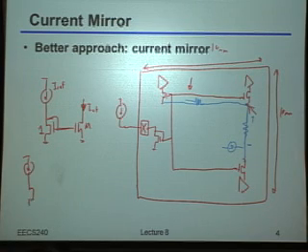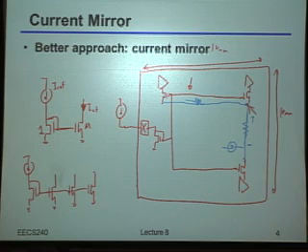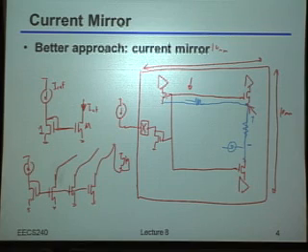Let's again take our external reference current. Okay? I'm going to mirror it here just to be able to create additional copies. So as an example, I'll take that same wire, I'll feed it to a bunch of these NMOS transistors, and then what you should actually route is the current. Okay? These currents are what you'd send out over the entire chip. Okay? Once they get to wherever it is you're trying to send it to, then, and I'll just wrap this around to make my drawing easier, that's when you connect it to a diode-connected device and mirror it.